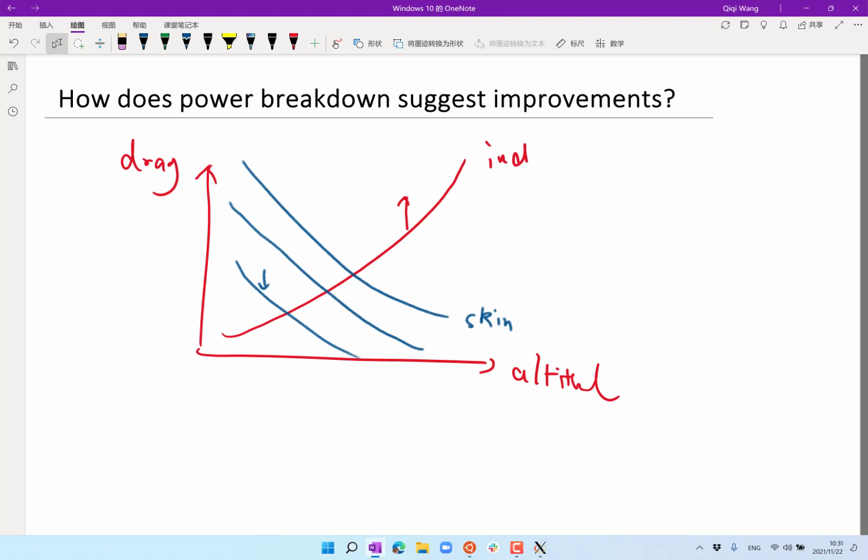You cannot, so at some point you are going to require an infeasibly high lift coefficient at the slowest speed you are cruising. Okay, I know all of you are doing this helicopter versus helicopter takeoff. So the slowest speed you're flying at in airplane mode usually basically is the highest speed you can go at in helicopter mode.